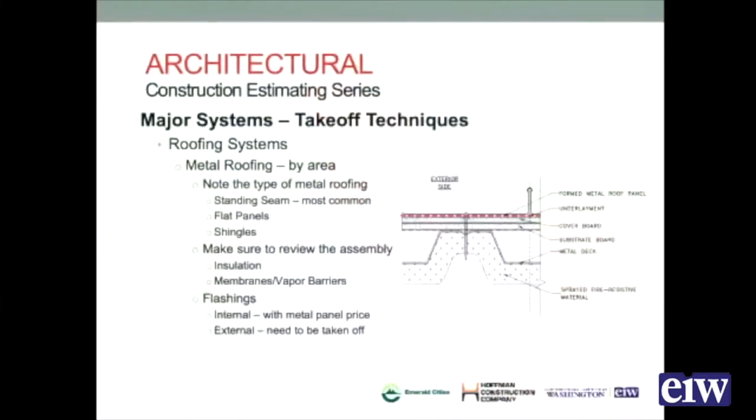You need to understand what system you're working with. Look at the specs, read that. You still will take these systems off in areas, and you'll understand those areas. You'll need to understand what kind of insulation, what kind of membrane or vapor barrier you need to put on underneath the system to build up that full assembly. And then you need to look at some of the flashings associated with that.